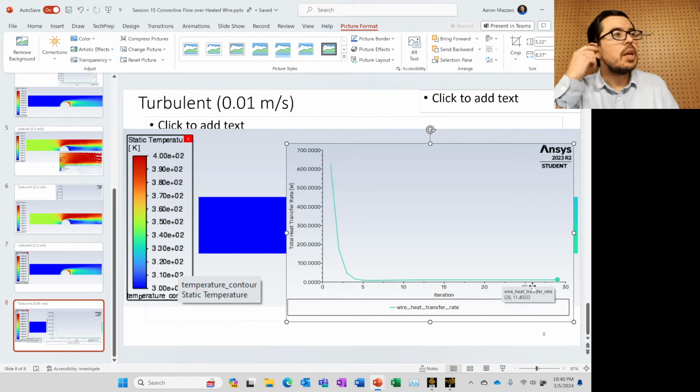This makes sense. If our goal is to heat a plate or something, and I have hot air at some temperature, I want to blow as much hot air on that surface as I can to get it to heat up more quickly. It's like a blow dryer. Do I use a low setting or a high setting? If I'm trying to get a lot of heat flux, I'm going to use the high.